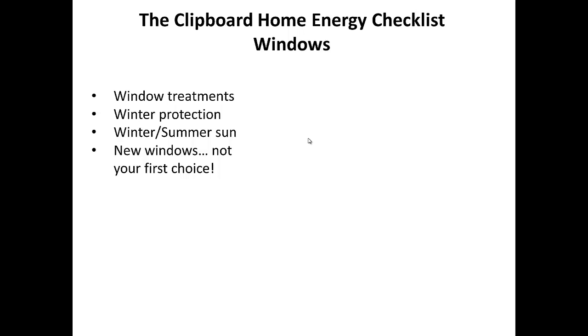air into the home. In the homes that I built, I made them extremely airtight, and we actually used a special device called an air-to-air heat exchanger, which helped bring in cold air from the outside, but it preheated it with the stale air that's being exhausted. So we were able to bring in 0-degree air, and by the time it got into the room, it was 50 degrees, and we're exhausting the stale air and bringing in fresh air. So just be advised that if you're going to do extensive work on your house and you've got an older furnace, you want to have that furnace checked.